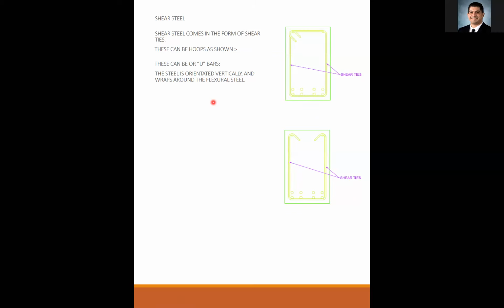Will they always have 2 legs? No. They usually have at least 2 legs, but we do joists that are fairly narrow pieces of concrete, and we just have 1 leg right down the middle. And we will also do beams. I've done beams on occasion that had so much shear on them, I couldn't make them work with just 2 legs. So I added another hoop here in the middle to get 4 legs. So that's a great question. It won't always be 2, but you can, it's again, the vertical legs, you count how many vertical legs you have for your design.